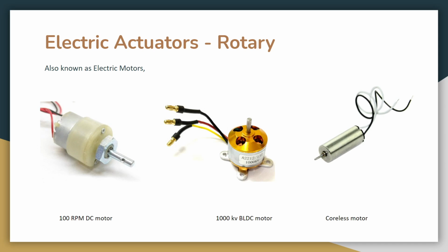That's exactly why heavy loading should be done on BLDC motors with a lower kV rating, usually 500, 600, maybe even 200 or 300 kV motors. Those motors rotate at a much lower RPM, and thus give higher torque.